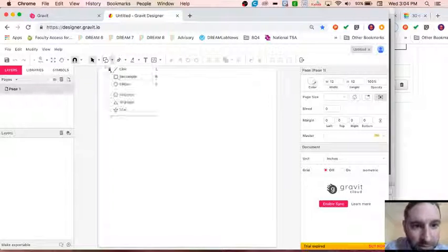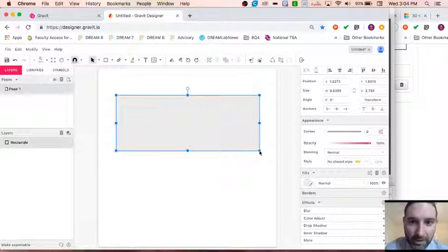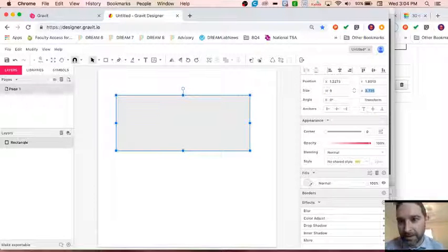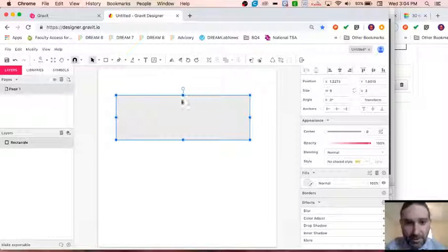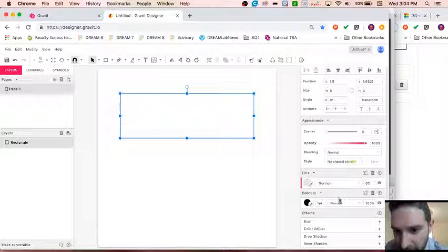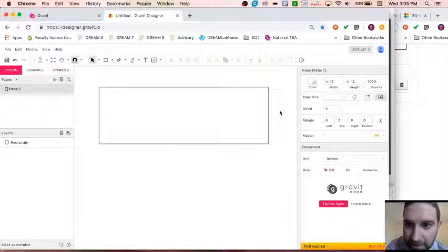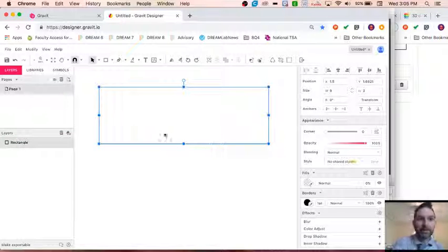So, first of all, we need to make our cut line for the panel. And I'm just doing a rough sketch of a rectangle. Right here we have a 9-inch rectangle, and we'll make that by 3 inches. That'll probably be enough for all the wording that you might want in there, and we can cut that on the laser. So we're going to take that down to 0% fill, and we're going to leave that border at 100%. And now let's just zoom in, so that's the majority of our thing. Now you could change the total width of this at this point, but you don't have to.